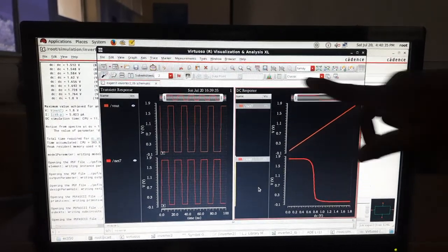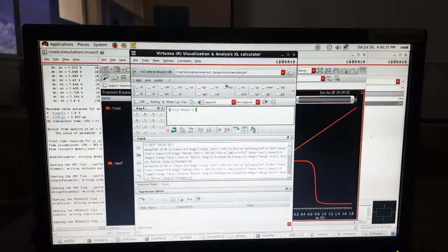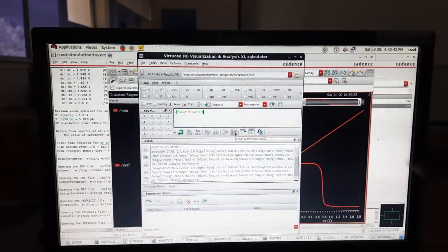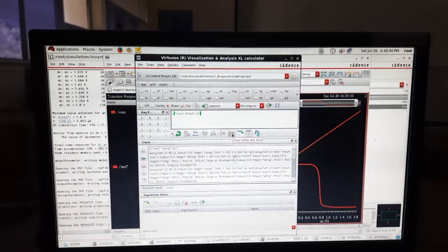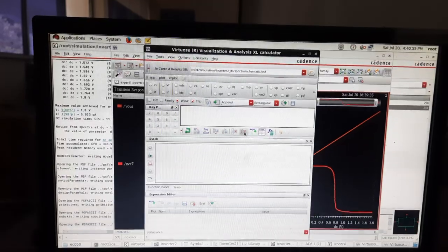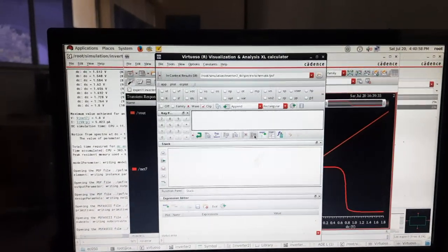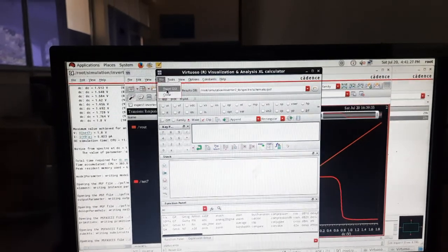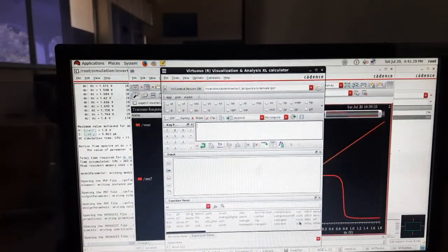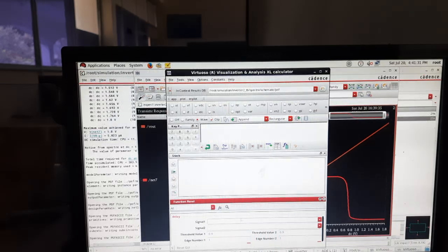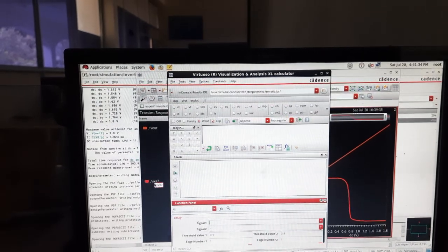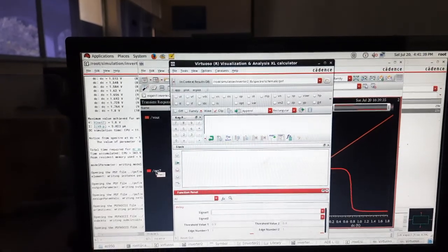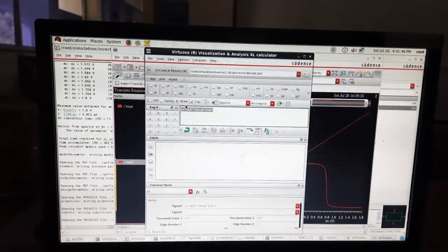Now go to the calculator. In the calculator waveform, you should click on clear buffer and stacks. Clear all stacks and buffer. Click on go to a file. Click on reset GUI. Then click on delay. Here we are copying and pasting net 7 and Vout. Right click on net 7, Control C.